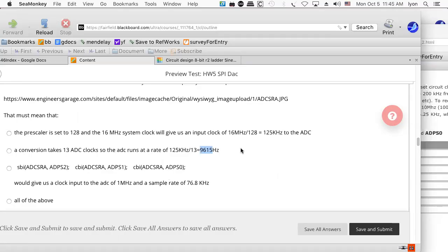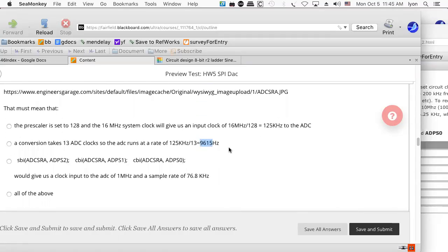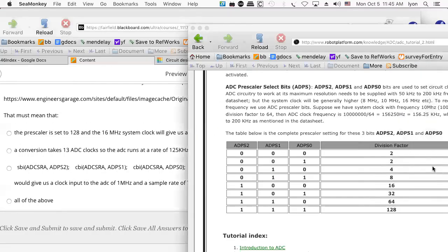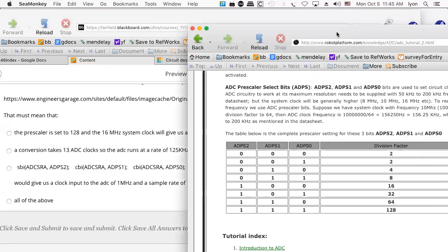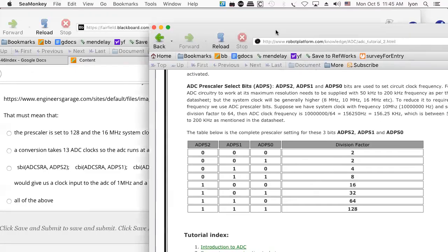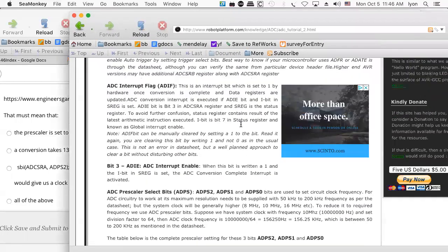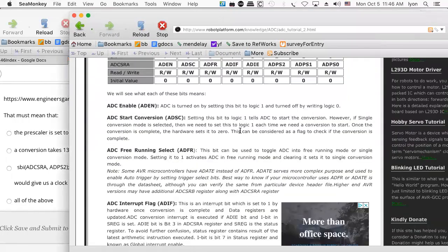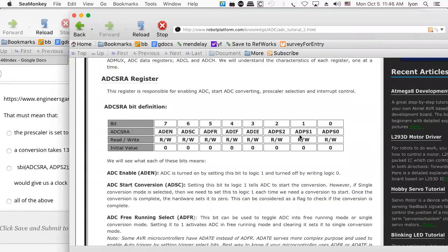And you know what's interesting about it is you kind of have to learn a lot about the A to D converter and the little bits that are being set. And now you can see why set bit and clear bit are so important, because what they're really doing is allowing you to change the sample rate of your A to D converter. And believe it or not, you got to go through the data sheets in order to be able to figure out how these things work.